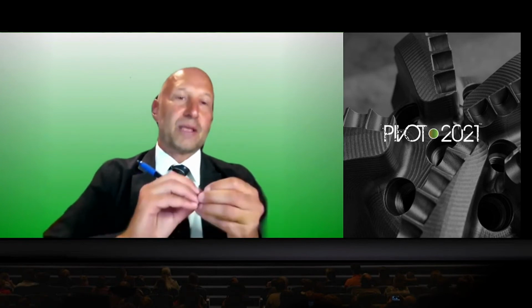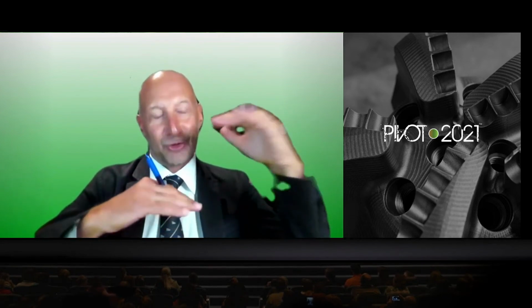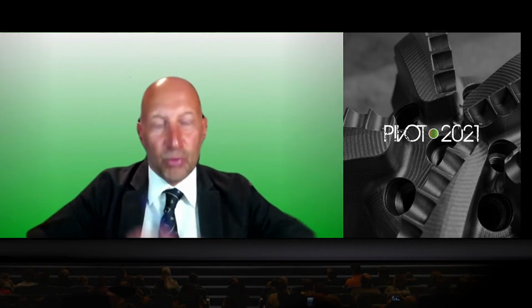But at the same time, we know that when the temperature of the water is relatively low, we are talking about 120, 130 degrees, a few degrees of temperature make a big difference in the thermodynamic cycle. So if you design a tailor-made solution, you can really extract a larger efficiency, because you work on a cycle that has a low temperature delta between the heat source and the cooling side. So it's a real balance between modularity and a custom-made solution. And if you can work well in this selection, you can offer the best solution.